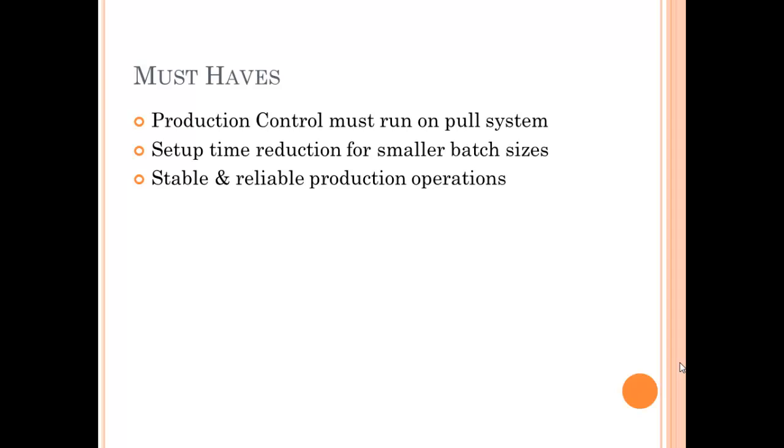Okay, so must have and just in time. You have to have a production control that runs on a pull system. You got to have setup time reduction because you want to run smaller batch sizes. And you have to have stable and reliable product operations.